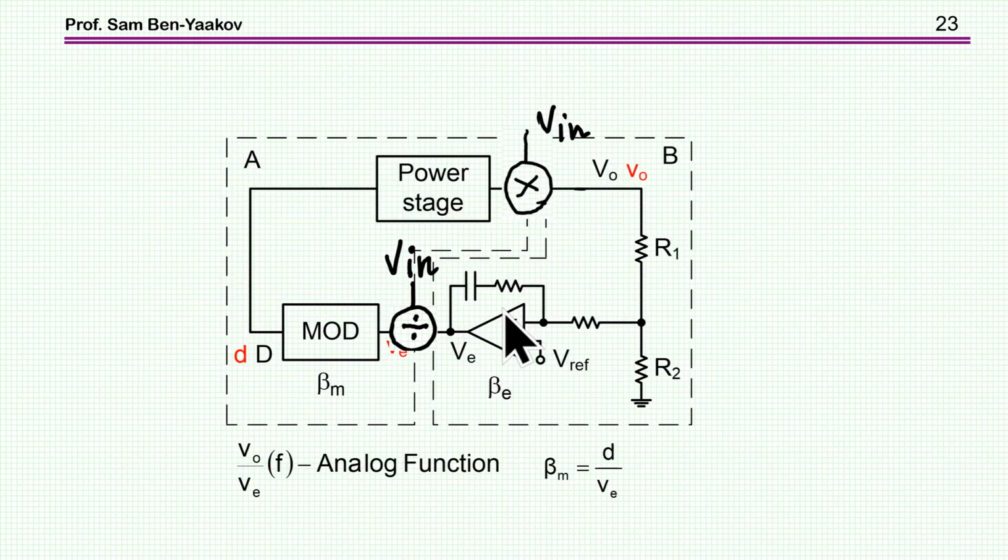So looking at it now with the simplified model that I had earlier, we know that the input voltage or the supply voltage is actually multiplying the gain here. But now we have a divider which is sort of neutralizing this. So this particular unit has a built-in correction, and this is why it's not sensitive to the gain margin.